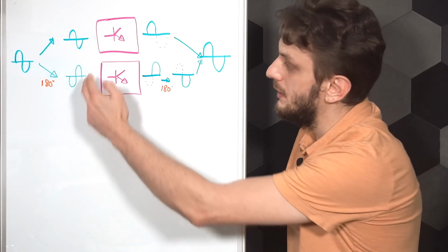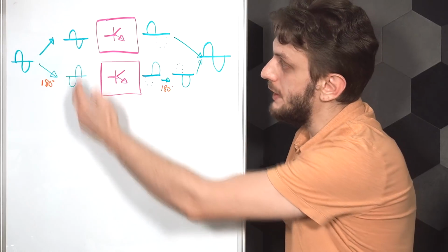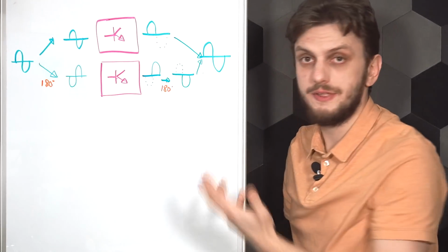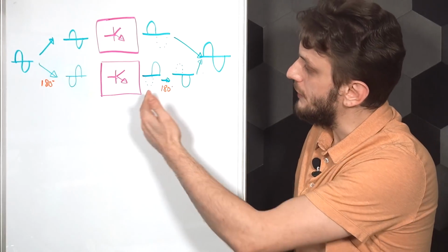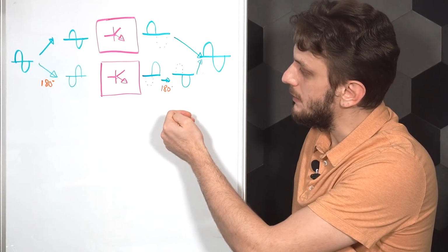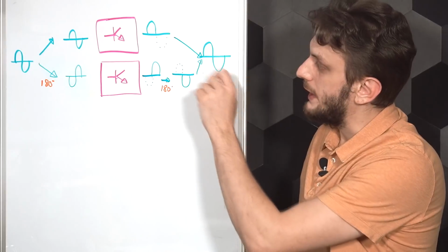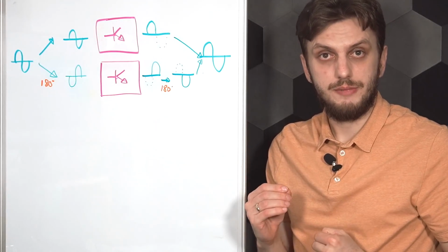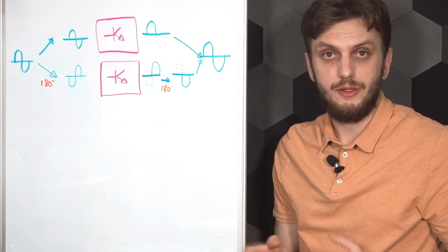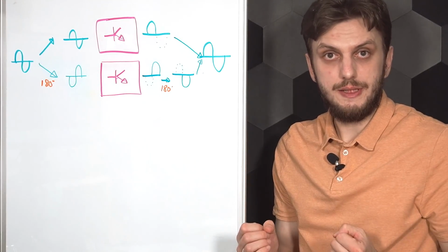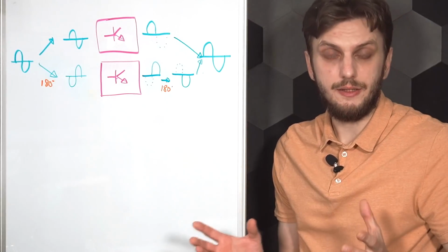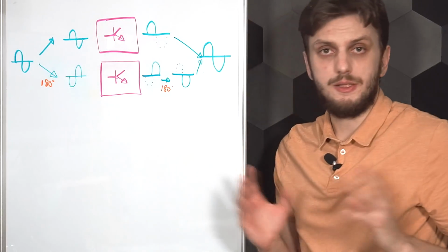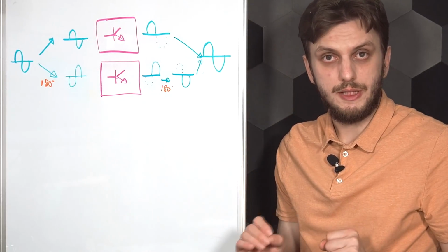So now we can take the same type of transistor amplifier, amplify the positive halves of the input signal, so we have both halves now, and then with a bit more phase shifting, reinvert the second signal, and then combine the two amplified halves to form the final output signal. Now, the main advantage of this setup is that it's far easier to find two transistors with matching characteristics if they're supposed to be identical to begin with. And typically, all of this phase inversion is done with transformers, although other methods can be applied.